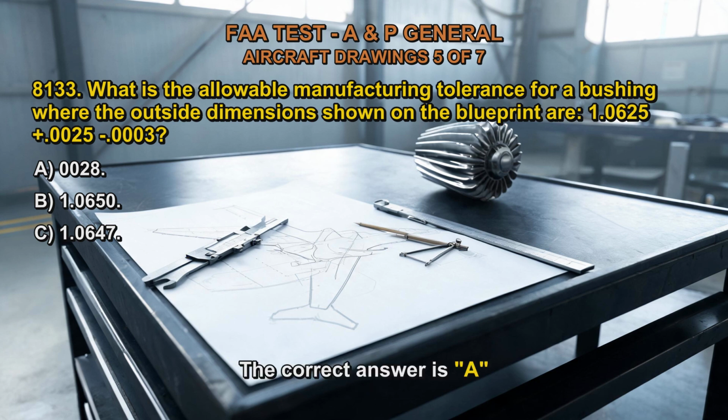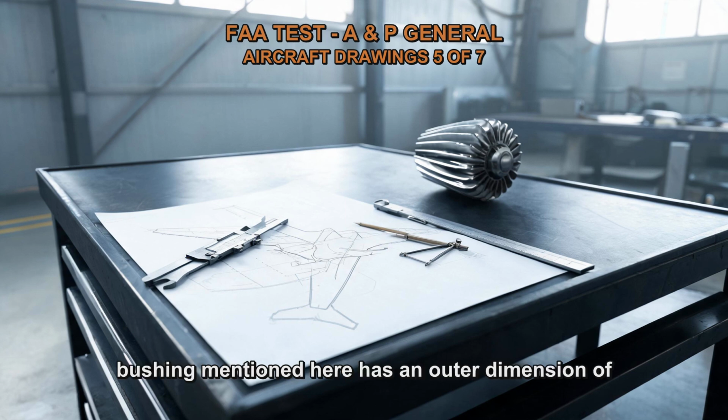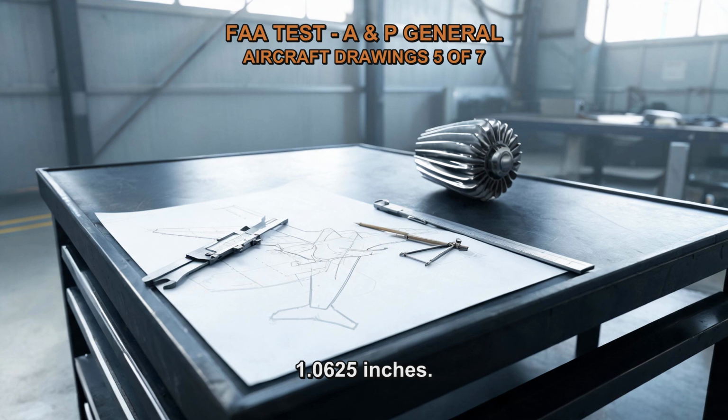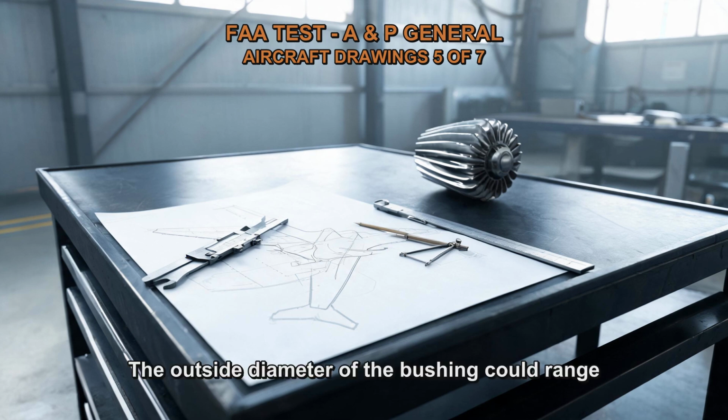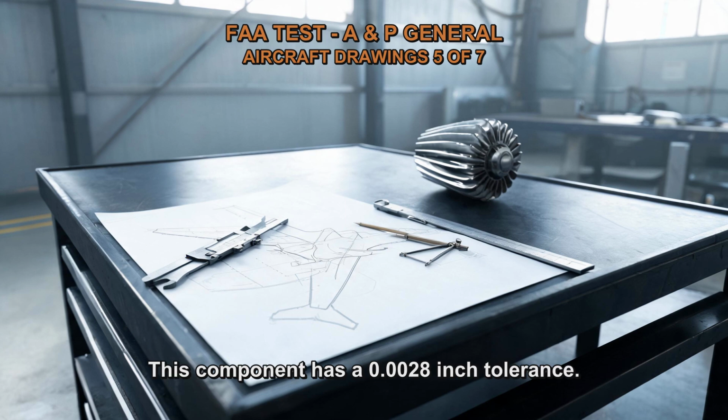The correct answer is A. With a tolerance of plus 0.002, minus 0.0003, the bushing mentioned here has an outer dimension of 1.0625 inches. The outside diameter of the bushing could range from 1.0622 inches to 1.0650 inches. This component has a 0.0028-inch tolerance.